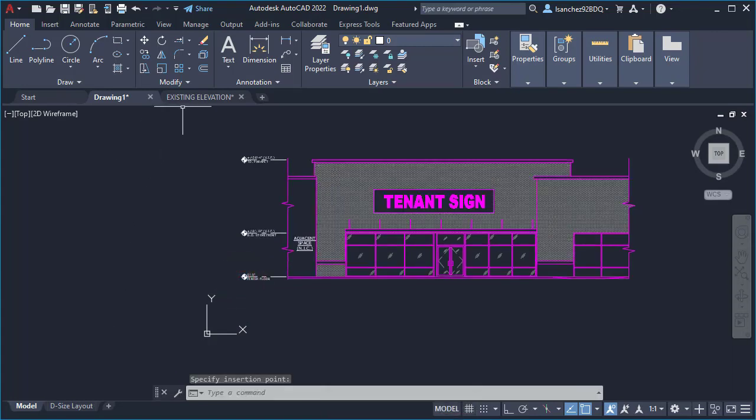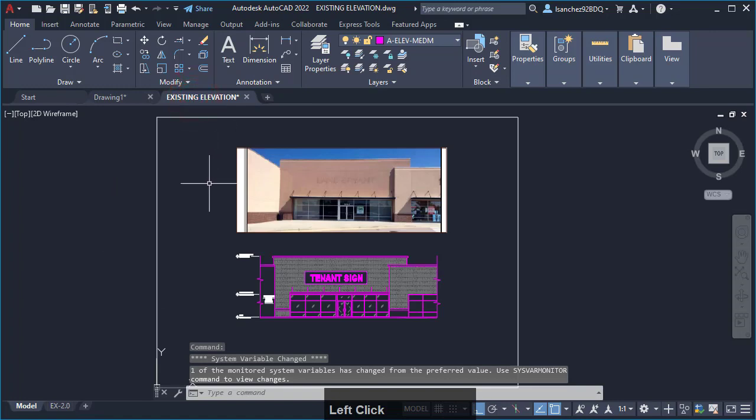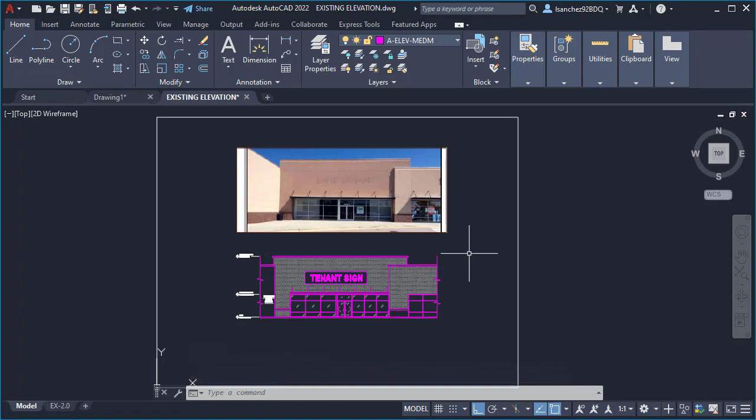Now if I go back to the other, I can save and close this drawing. So I'm gonna show you another command for saving your drawings, right? You can go here on the quick access panel. This is called the quick access panel, and you can click the save command to save your drawing, or you can also use the shortcut Ctrl+S to use the same command, QSAVE.